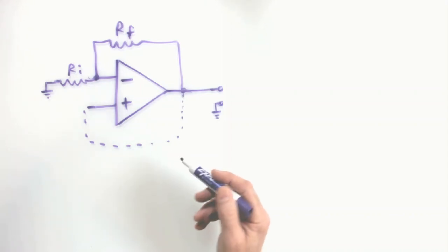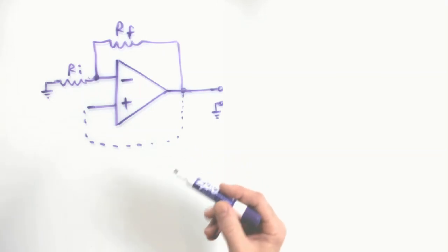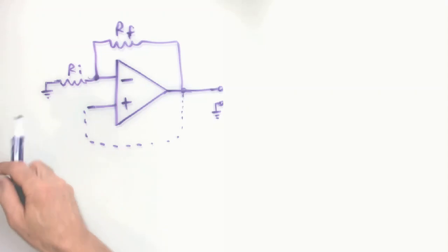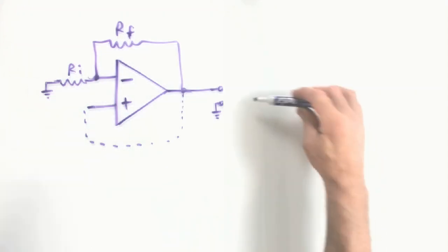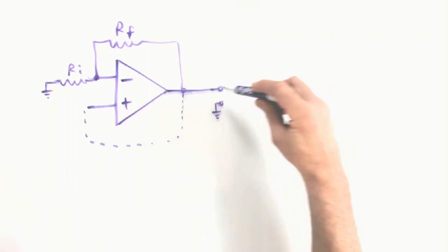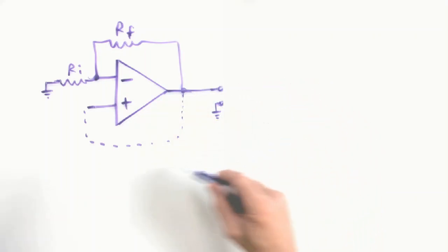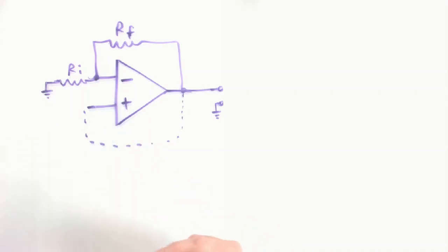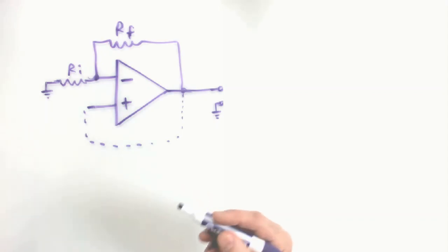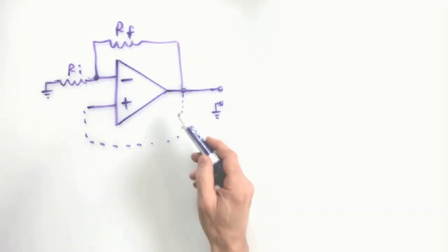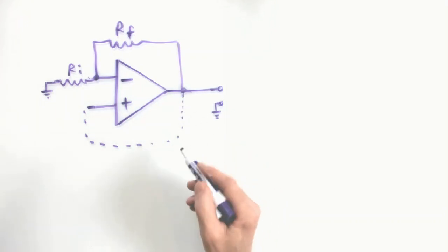It's very much like if you took a microphone, which was the input to an amplifier, and you brought it around in front of the speaker, which is the output. So the output of the amp is coming into the microphone and being fed back to the input, and you'll get a sustained oscillation, the squealing or whatever is coming from the system. But it's a sustained oscillation. So it's very much the same thing.